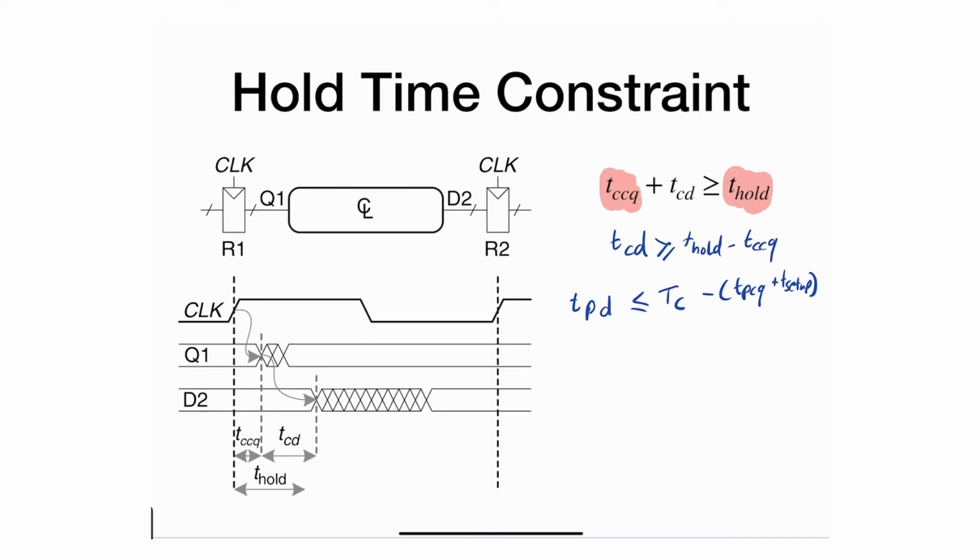That's what it's telling me. So there's a range of numbers that is acceptable, so that you have the setup time and the hold time not violated, so that they're actually maintained. And another thing, if you take a look at this equation, you'll see that TC, the clock period, never appears in it.